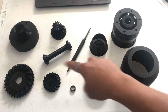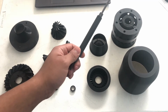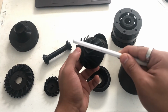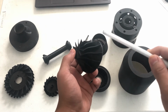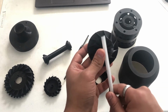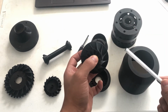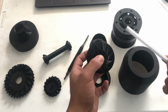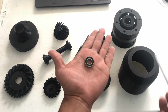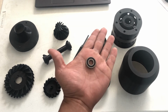I will explain the function of all these pieces. The shaft. This is responsible for delivering all the force generated by the turbine to the compressor. The compressor. This piece is responsible for delivering the air while it is compressed, increasing its pressure. The angle of the vanes can be set between 10 to 30 degrees, and this can affect the efficiency of the engine. The bearing. This part must be able to withstand high temperatures because its function is to eliminate friction, supporting the shaft and transmitting the movement force.